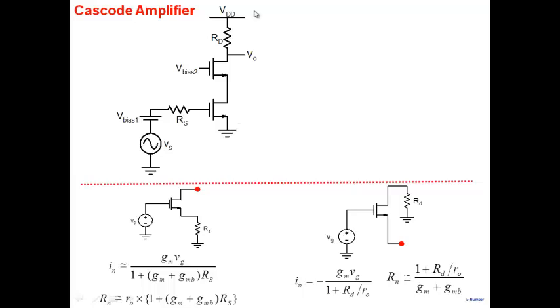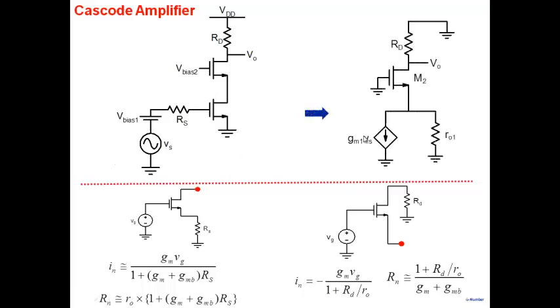So if we look at this particular amplifier, we note that if we focus on this part here, it looks like this one here. So this whole part here, I'm not talking about this part here, from here down to here, can be replaced by a Norton's current source and a resistance. So at this node here, we have built a Norton's equivalent. Of what? Of which part? The lower part here. And so it's a Norton's current and a Norton's resistance here.